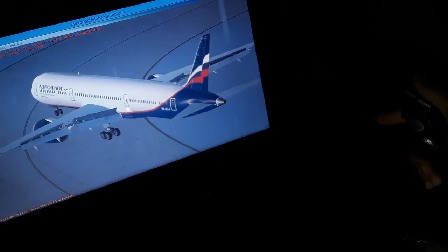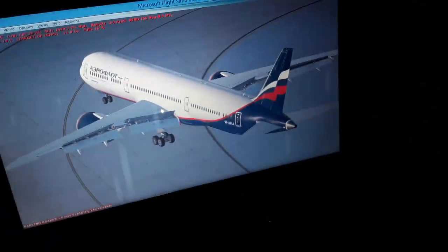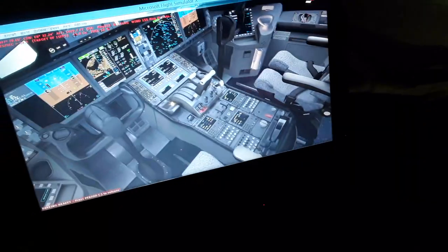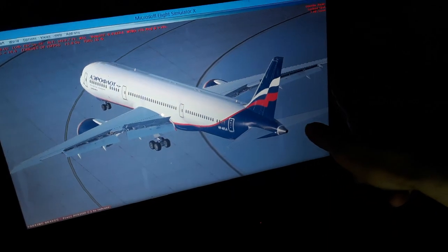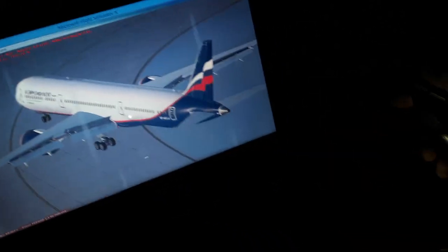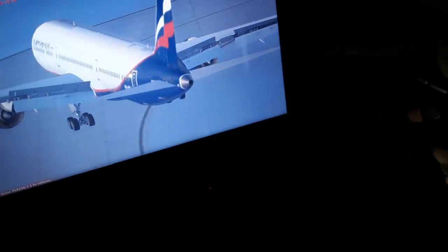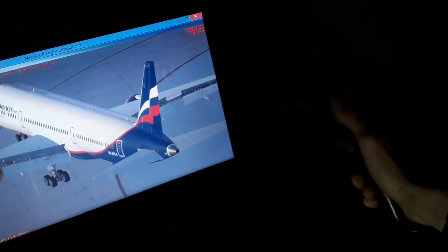In the air you have the rudder, so the rudder pedals again. We also have over here another axis, from wingtip to wingtip, which is the pitch axis of the aircraft. In the pitch axis you use the elevator of the horizontal stabilizer for climb and descent.